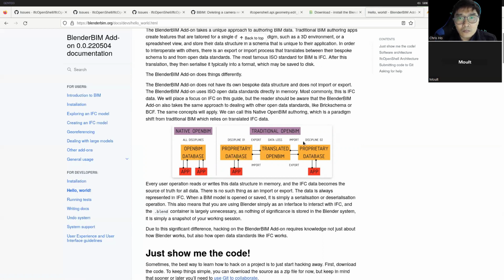And then you press an import or an export button, and you can think of that as translating from one language to another. And there's a lot of information lost in that translation because the two languages are not equal. It's as simple as that. And that's why when many people try to collaborate with IFC, there's a lot of pain involved because they lose a lot of information. And very often, because of that information loss, we don't trust it. We say, this is your native application.